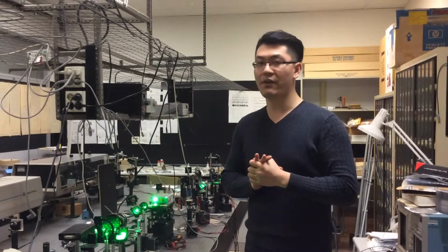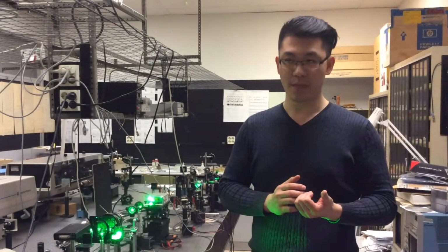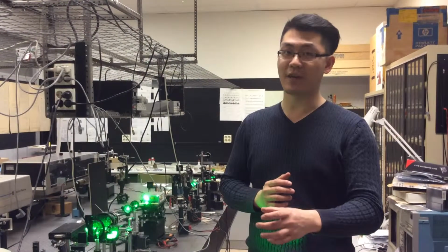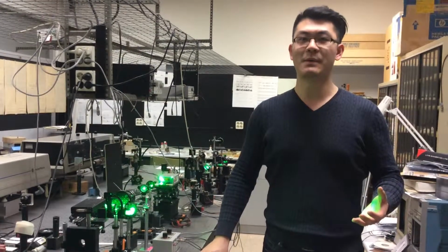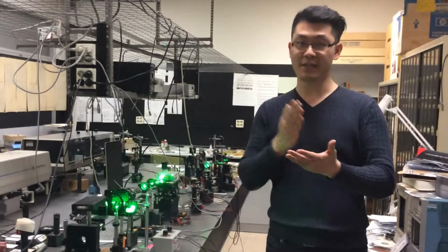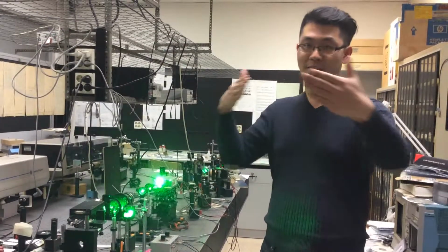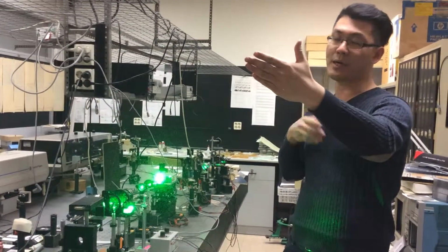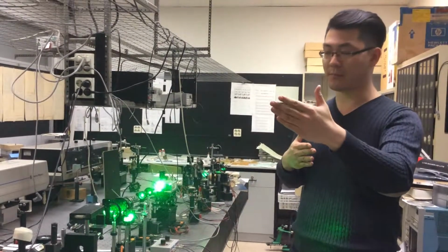In our case, we are looking forward to realize dynamic wavefront modulation. So we are using a liquid crystal on silicon display. Well, this element is also referred to as a spatial light modulator. And how does a spatial light modulator work? Well, in this case, we can generate a certain phase configuration in the liquid crystal on silicon display. So the light passed through, or in this case, reflected by this spatial light modulator, is modulated.